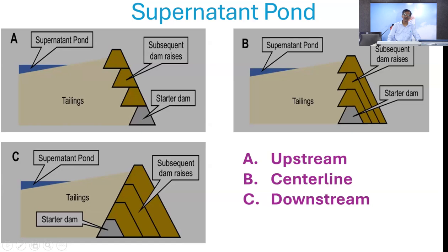Yes. We have the first raising of our ash dike, which consists of both upstream raising in some portions and downstream raising in some portions. It is not centerline. Upstream raising on the west side of the dike, and on the east side of the dike we have downstream raising. Say suppose there are four boundaries: in one boundary you have done downstream, and in another boundary you have done upstream, because the other two boundaries are surrounded by hills.